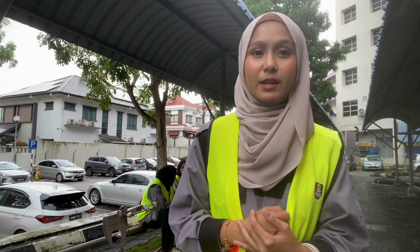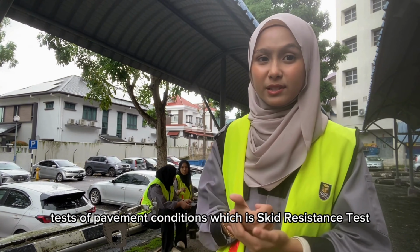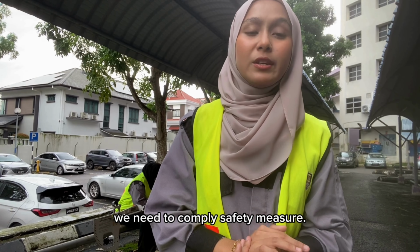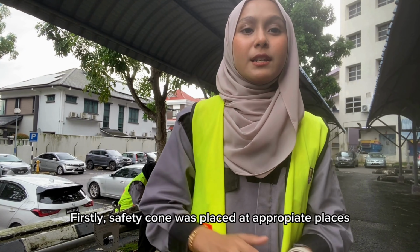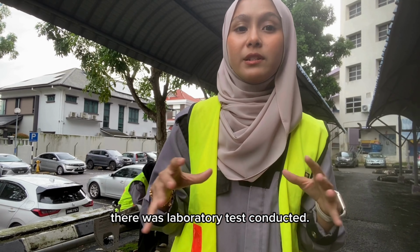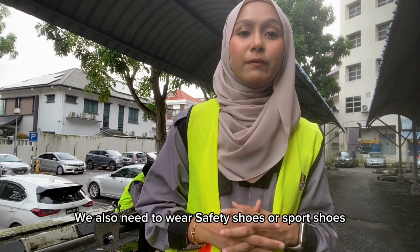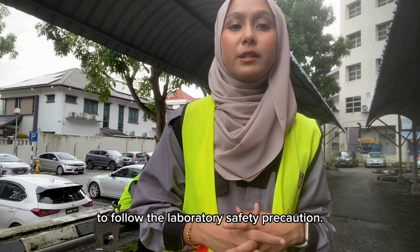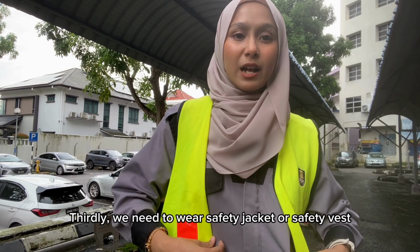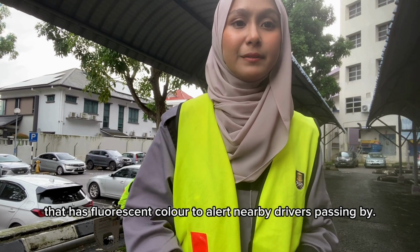road infrastructure. In this RSA, we will conduct 3 essential pavement tests, which are skid resistance, sand patch method, and outflow meter test. While conducting the laboratory test, we need to comply with safety measures. Firstly, safety cones were placed at appropriate places to alert drivers that there was a laboratory test being conducted, as shown here. We also need to wear safety shoes or sport shoes to follow the laboratory safety precautions. Thirdly, we need to wear a safety jacket or safety vest that has a fluorescent color to alert nearby drivers passing by.